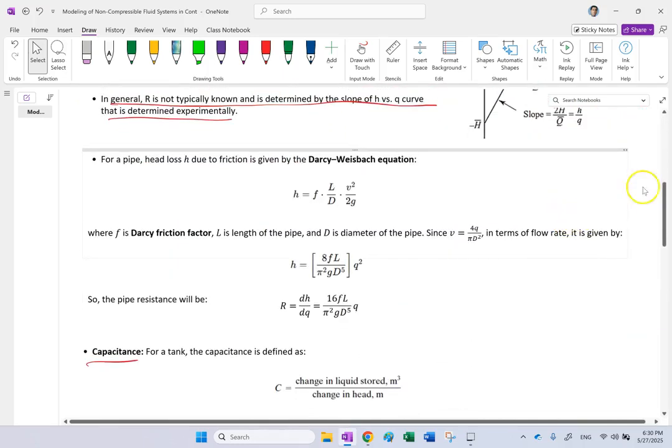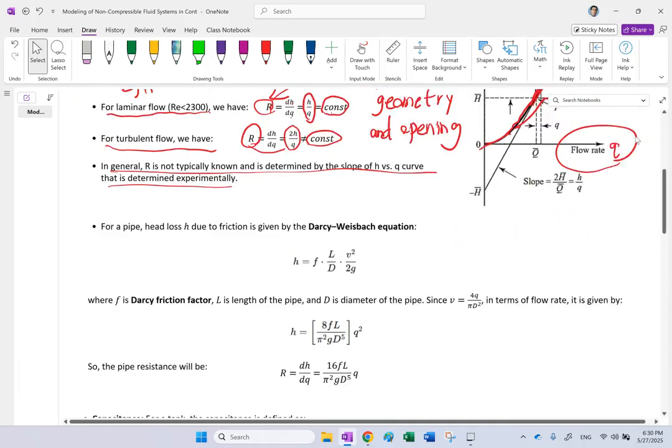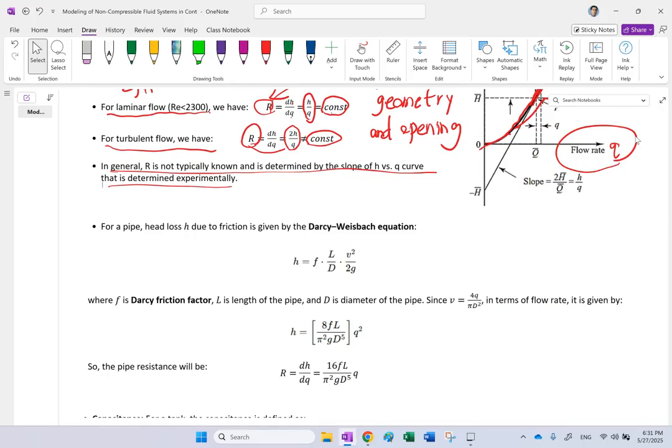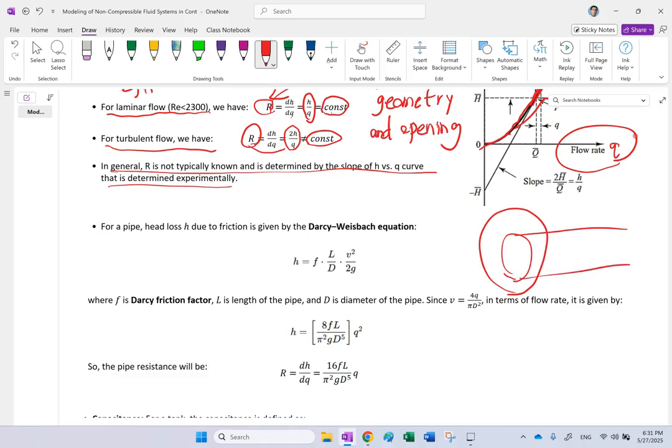Now, what about the pipe? We know that when the fluid passes through a pipe, always the pressure of the fluid drops. Why? Because, of course, your pipe interior, the inner diameter of the pipe, regardless of how smooth it looks like, if you look inside of this inner diameter, there is a bunch of surface roughness, right?